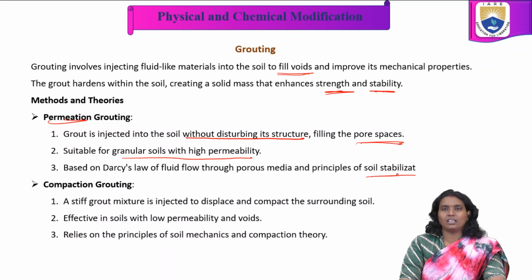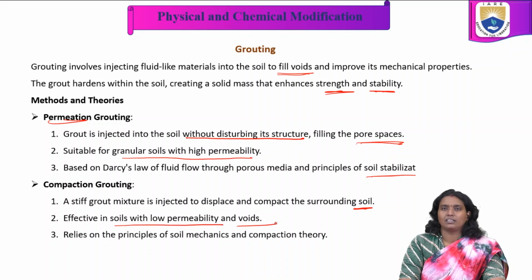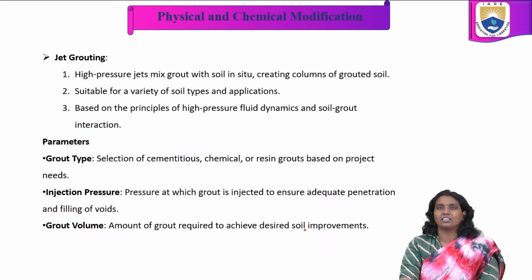Coming to the compaction grouting, a stiff grout mixture is injected to displace and compact the surrounding soil. It is effective in soils with low permeability and voids. It relies on the principles of soil mechanics and the compaction theory.